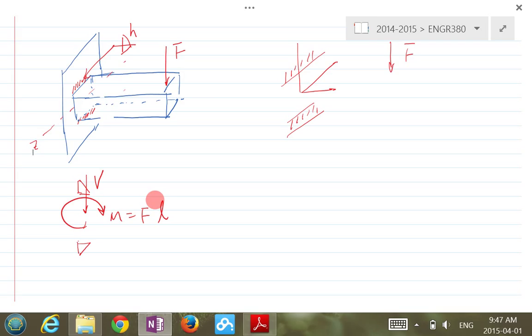It is J. So when the rotational axis is perpendicular to the plane where the geometry is in, you call it J. And now the whole thing is rotating about this different rotational axis. Then this time we're not going to call it J anymore. We're going to use I now, right? The second moment of area basically. So just bear in mind the difference.